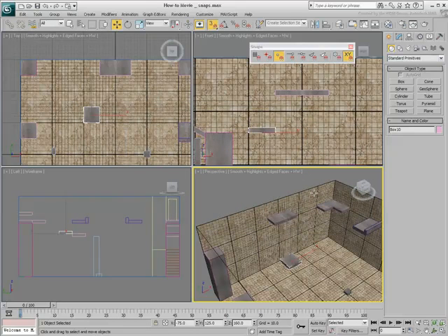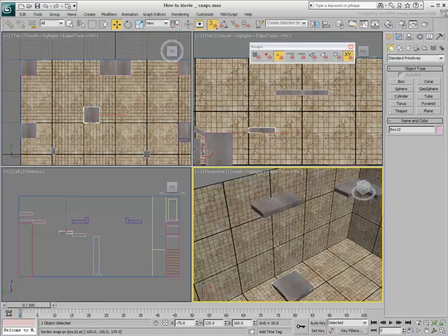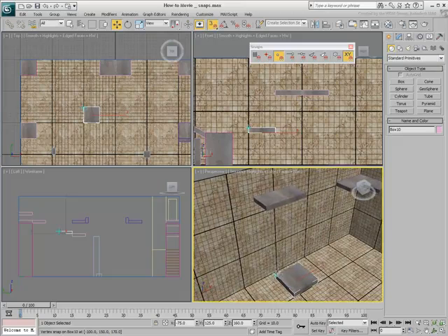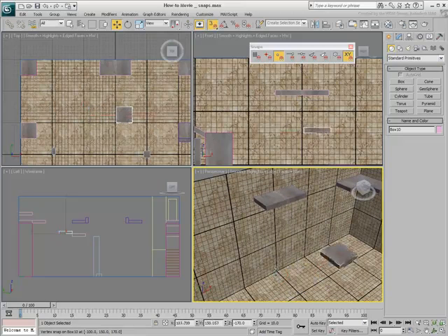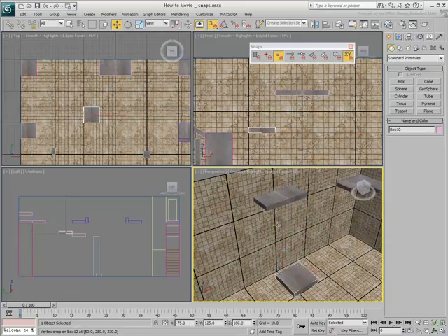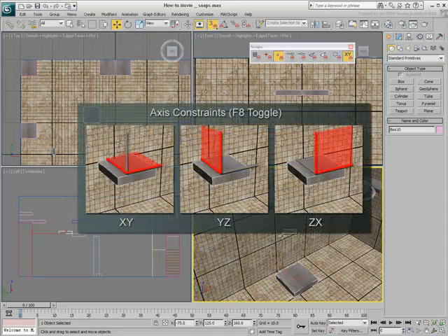Using 3D Snap in vertex mode, notice how you can align a vertex to another while the object travels in one direction only. It is important to note that this mode also works in two directions simultaneously. This in effect replaces the 2.5D mode you learned about earlier. To set this mode to work in two axes simultaneously, use F8 to move between the XY, YZ, and XZ planes.